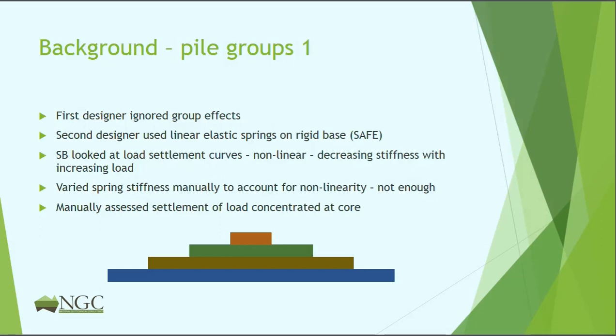Well, the first designer had certainly ignored any group effects. He just said all the piles are equally loaded. The second designer was using the SAFE program, which some of you may be familiar with. It's a module of the ETABS structural software. And of course, like most structural software, it says that piles are linear elastic springs on an infinitely rigid base.